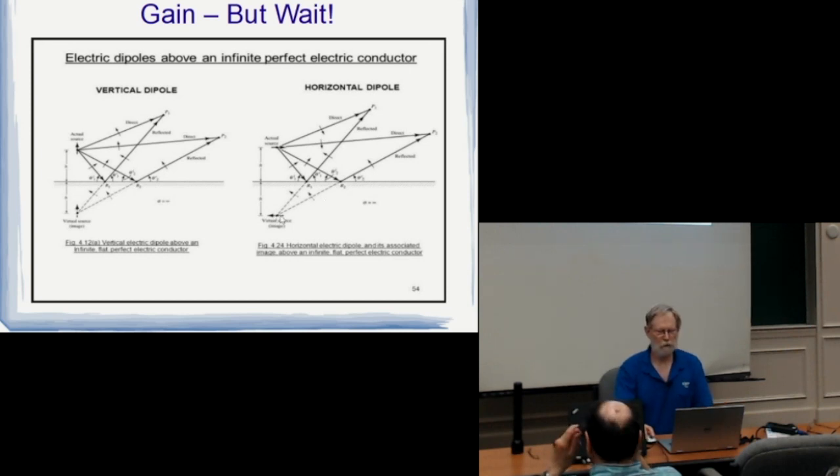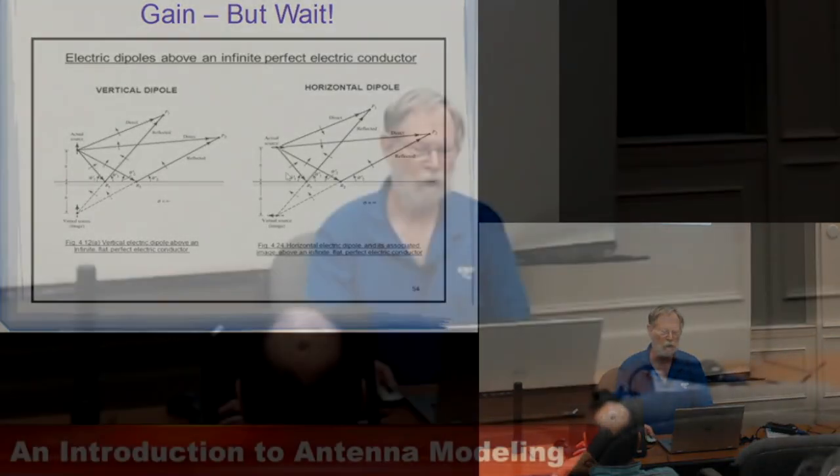And because it's opposite in phase, can anybody tell me what you would see if you were right on the horizon? Exactly, nothing, cancellation. The two signals would cancel out. So that says you're going to get no signal right at the horizon. And that makes sense because you can't get any signal down below the horizon, underground. All of the energy has to be concentrated into the hemisphere above ground. And so therefore you're getting some gain out of that.